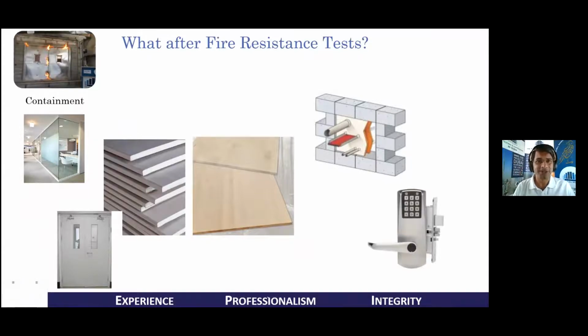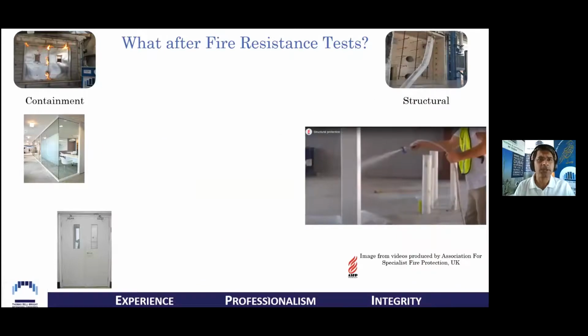When there are through penetrations for utilities, which are cut and brought back together to a fire resistant system, there has to be some method to make sure that they will continue to be fire rated. And the same goes for the structural fire resistance that we are talking of, that not only is it important to understand that the chemical or the element that was used to create the property is able to maintain repeatability, but also repeatability is maintained while installation is being done.